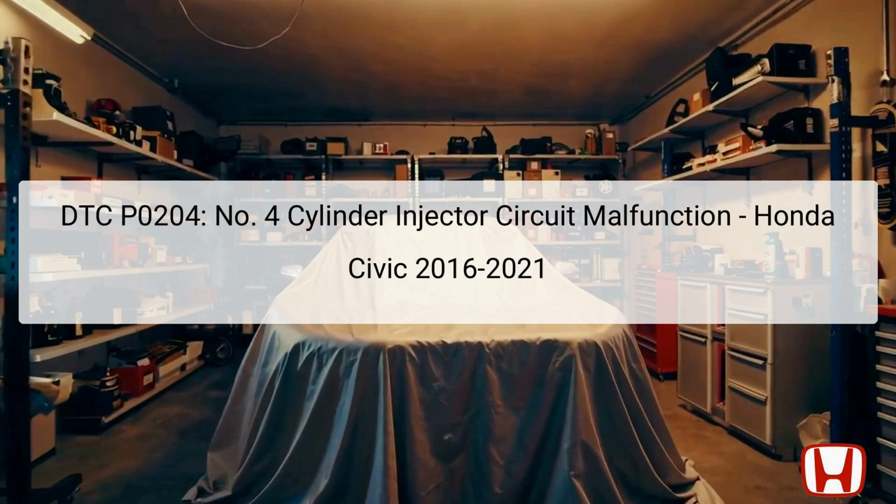The diagnostic trouble code, DTC P0204, indicates a malfunction in the number 4-cylinder injector circuit in the Honda Civic models from 2016 to 2021. This specific error reflects issues that can arise within the fuel injection system, which is part of the powertrain control module, PCM. The PCM controls the operation of fuel injectors based on various engine parameters it receives from sensors. The 4-cylinder injector specifically corresponds to the injector responsible for delivering fuel to the 4th cylinder of the engine.